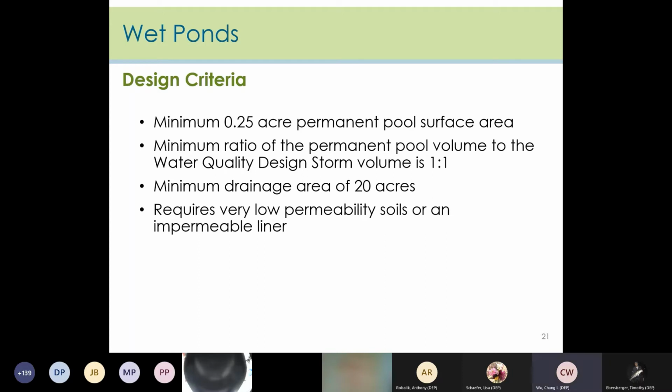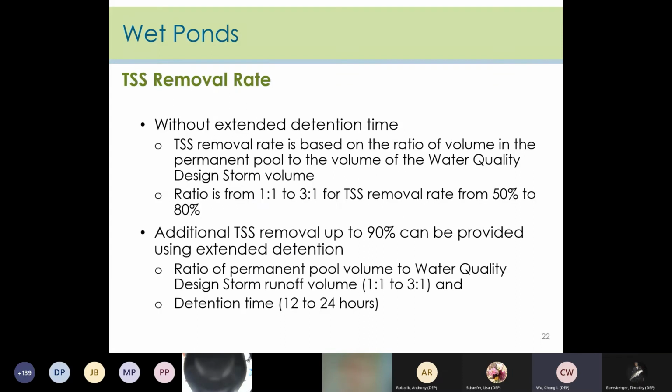The soil needs to have a very low permeability rate, or you need an impermeable liner underneath the pond.